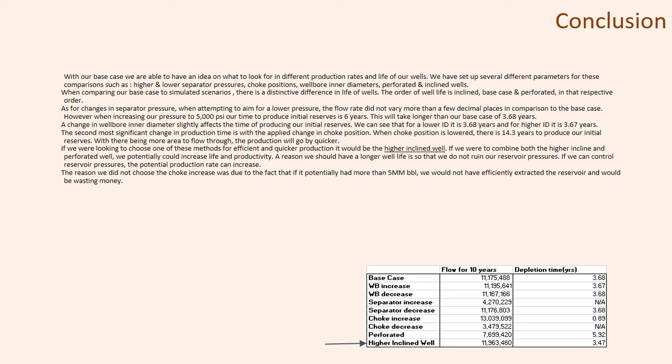We have set up several different parameters for these comparisons, such as higher and lower separator pressures, choke positions, wellbore inner diameters, perforated and inclined wells. When comparing our base case to simulated scenarios, there is a distinctive difference in life of wells. The order of well life is inclined, base case, and perforated, in that respective order.